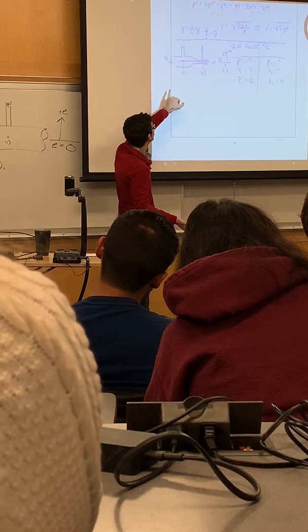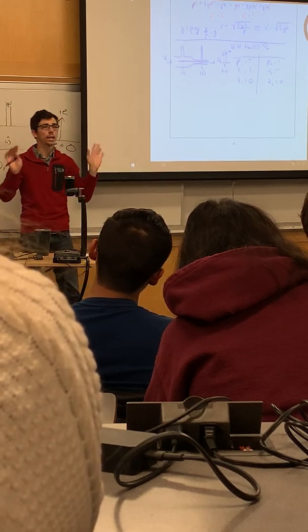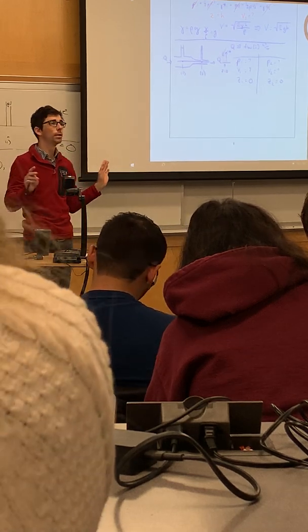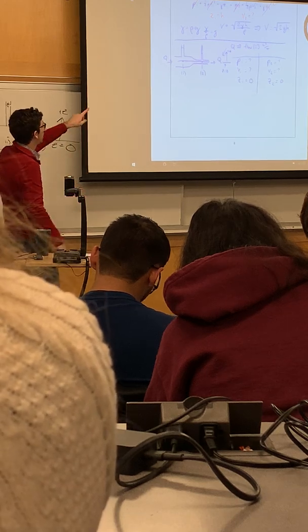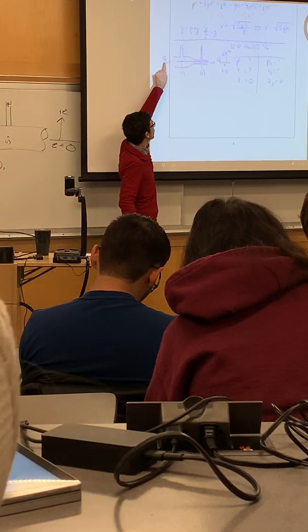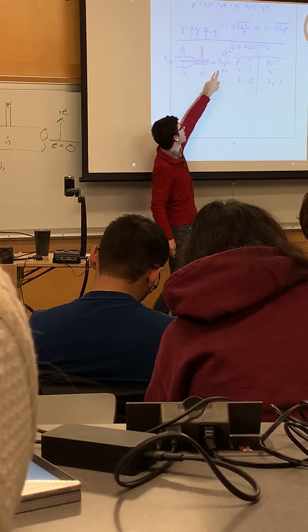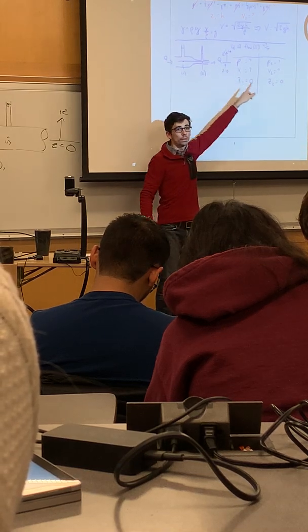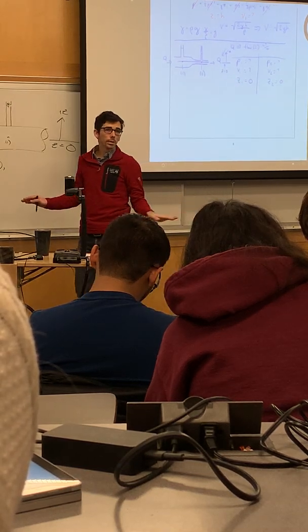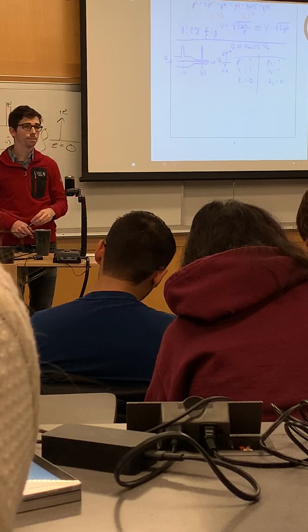So what we need to do is, our assumption is that the density of the fluid can't change. So in this example, we have Q entering has to be the same as Q leaving, right? So we can't change the flow rate because of our assumptions of the Bernoulli equation.